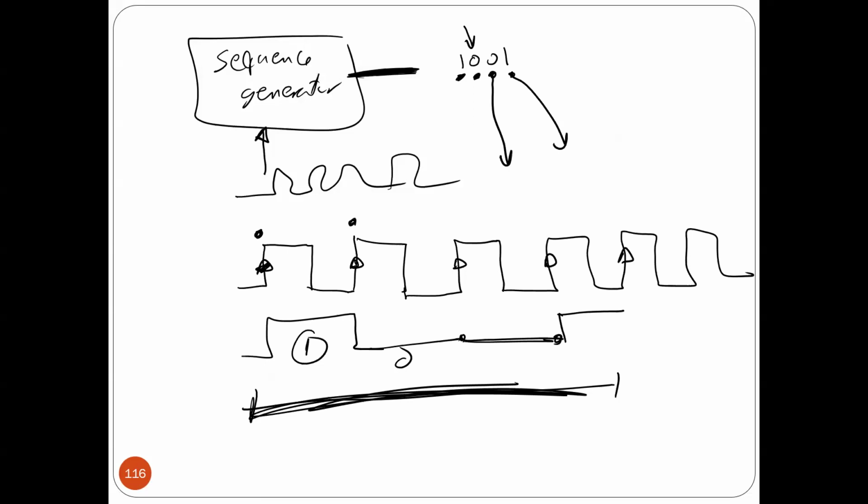In the coming project, if you want to visually see the sequence, you have to make the clock very slow. For example, if I connect an LED here, with a resistor, I want the LED to turn on when the output is 1 and turn off when it is 0.